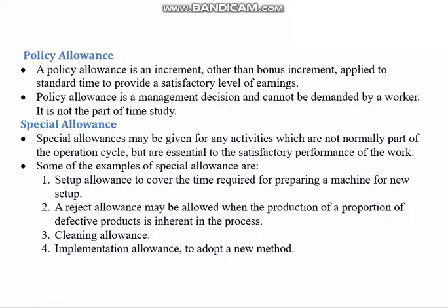But the policy allowance and the special allowances are not part of the time study, yet these allowances are to be taken into account. They are not only for specifying the standard time. They may be necessary even for calculating the wages of the workers also. Here some examples are given for special allowances. Setup allowance covers the time required for preparing a machine for a new setup.